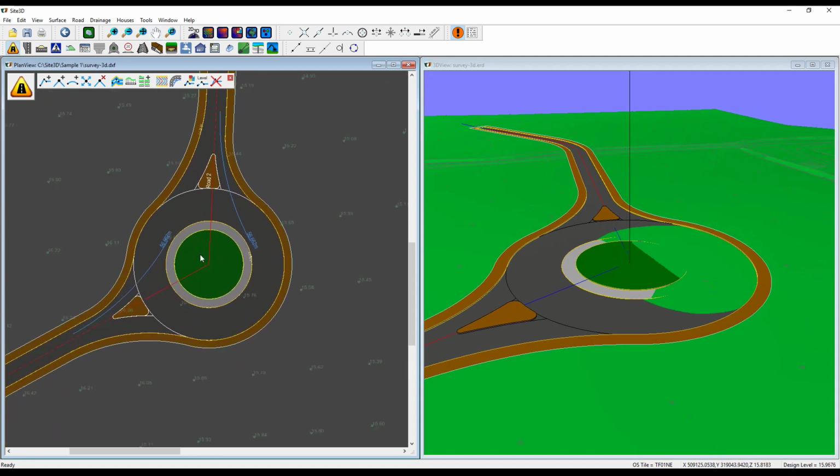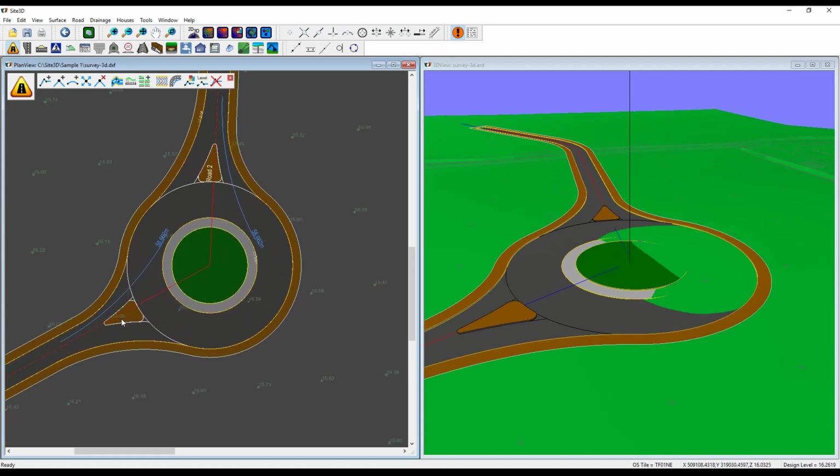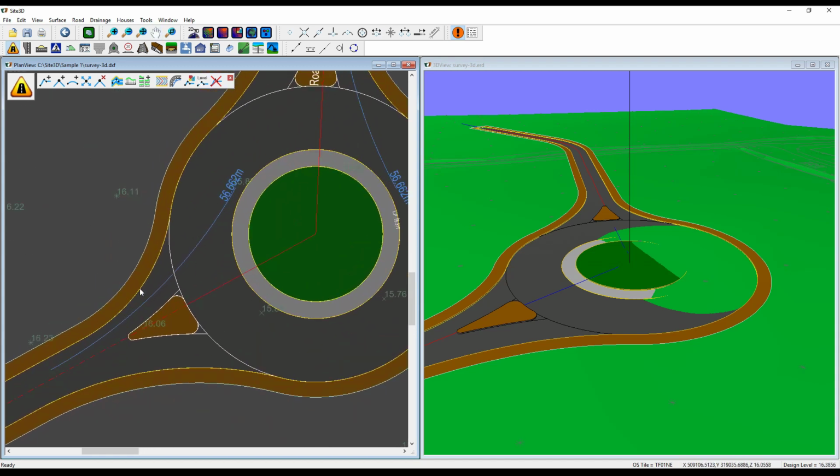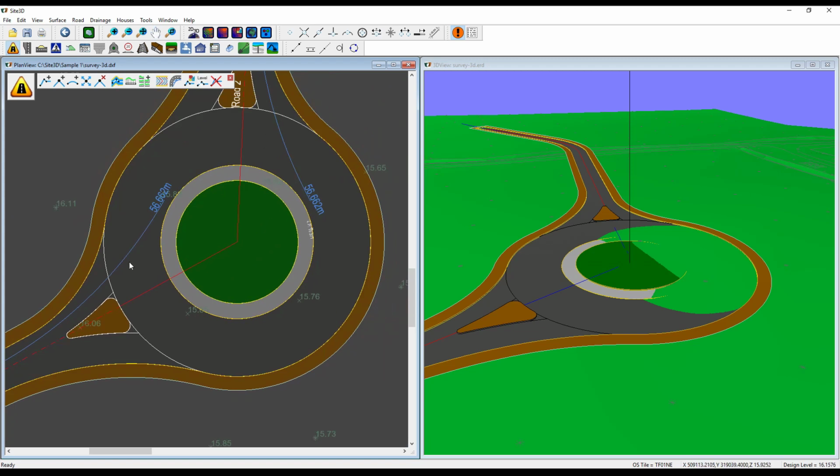On the plan view, you can see we've got our two roads, we've got our splitter islands, we have these blue lines here with the radius. These are our maximum deflection. This is highlighting 1 meter off the centre line here, to 1 meter off the channel, to 1 meter off the inner island. This is sort of the worst case scenario if a driver tried to enter the roundabout ignoring any white lines. That is the maximum sort of path they could take. So it shows you we are within the realms of reasonable here. We are underneath the 100 meter max, what we defined in the properties.